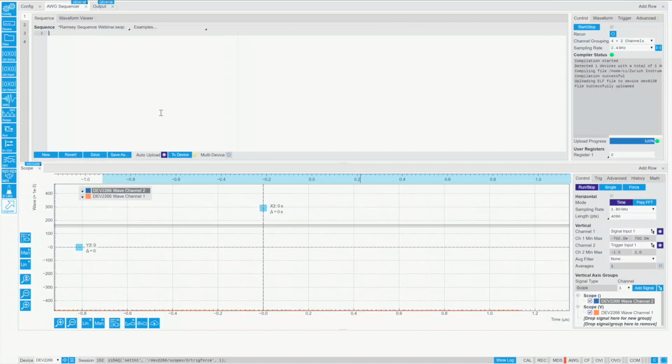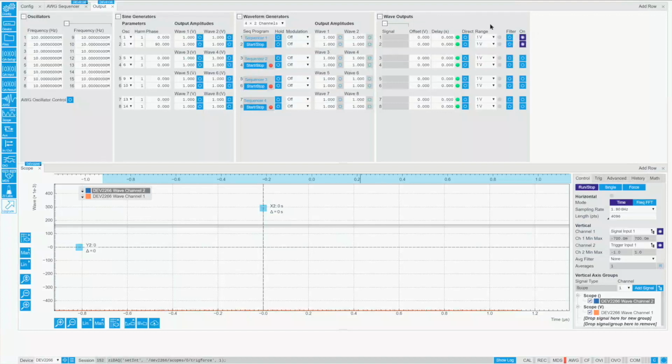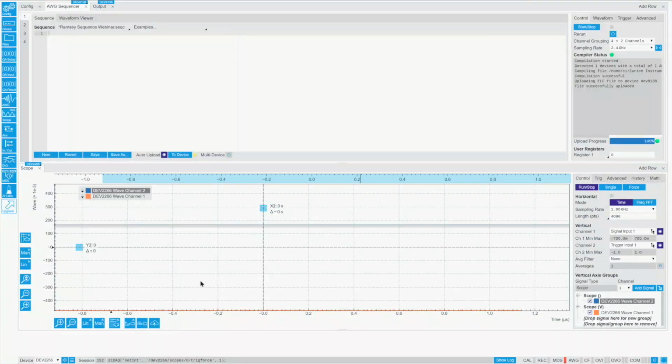Of course, you can connect several instruments together. So what we have here connected now and opened is from the AWG, the sequencer tab. This is where we write our AWG program. And we also have the output connected, in which we can control the voltage range and whether it should output something or not. In the bottom, we have the oscilloscope visible from this quantum analyzer, and this is what we'll use to display our results. Good, so let's start with writing our Ramsey sequence.